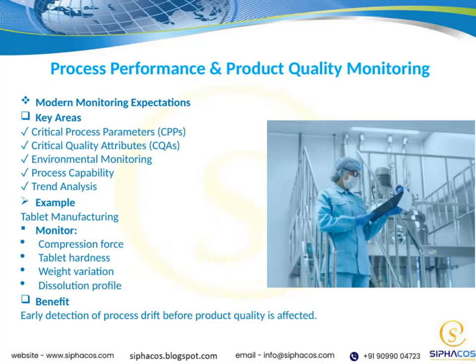Let's talk about how we keep a close eye on both process performance and product quality. Modern monitoring focuses on several key areas: critical process parameters, critical quality attributes, environmental conditions, process capability, and trend analysis. For example, in tablet manufacturing, we track things like compression force, tablet hardness, weight variation, and dissolution profile. This approach helps us catch any process drift early, before it impacts the quality of the final product. It's all about staying ahead, not just reacting.